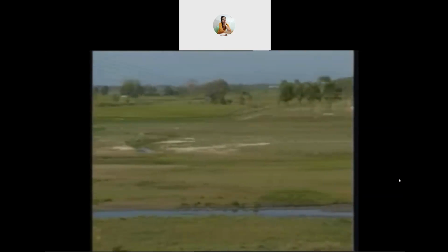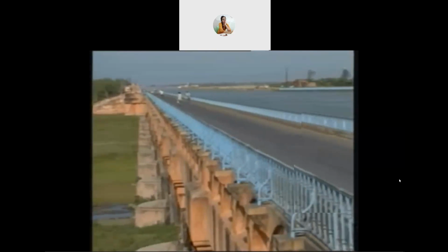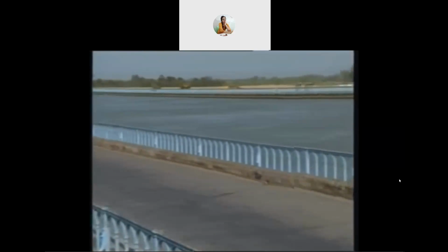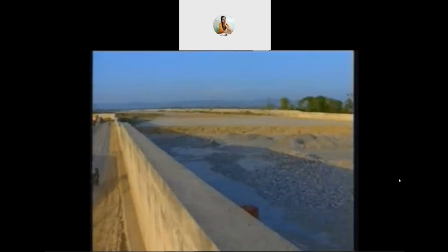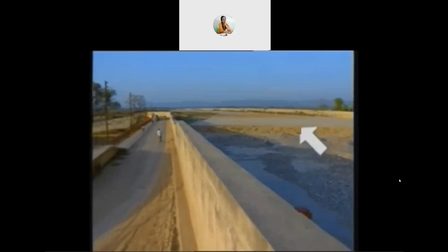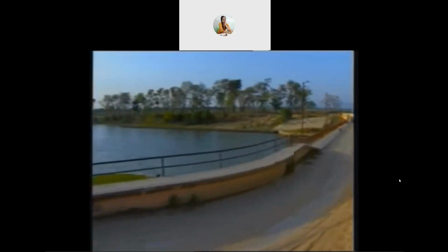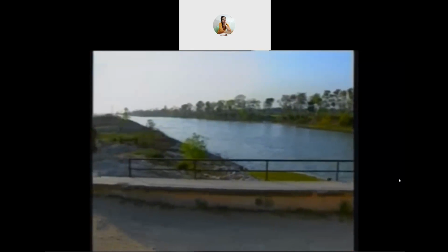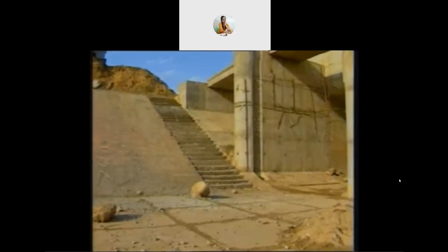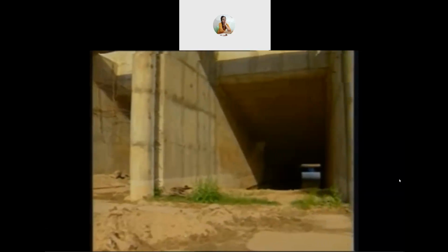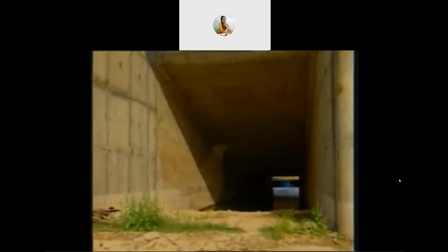An aqueduct is preferred when the drainage is wide and of higher discharge capacity, and the water flows for longer durations. But the situation may be reversed as well. When the bed level of the river is higher than the canal bed level, a super passage is constructed. It is a case when the canal is in deep cutting. However, when the headway clearance between the river bed and canal supply level is small, a canal siphon is built.